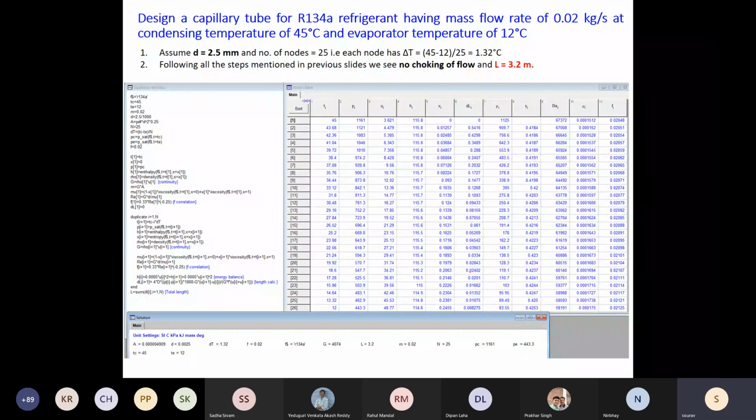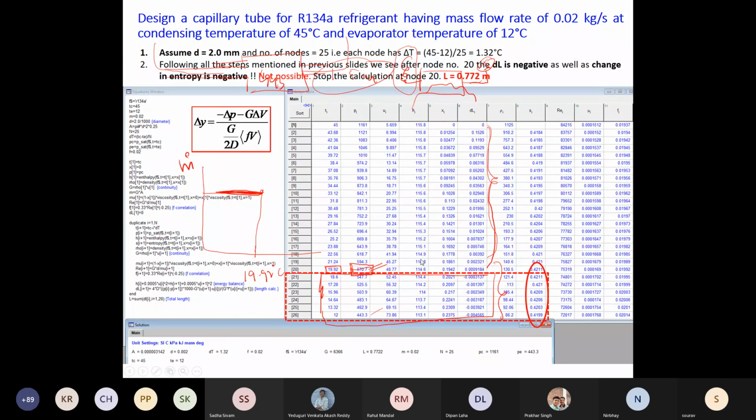Okay, so you can see that going with the larger diameter ensured that your velocities are lower. Earlier, the velocities were more or less at this value at 19.9. This velocity is called the critical velocity. It is a function of operating condition, it is a function of the fluid which is used.